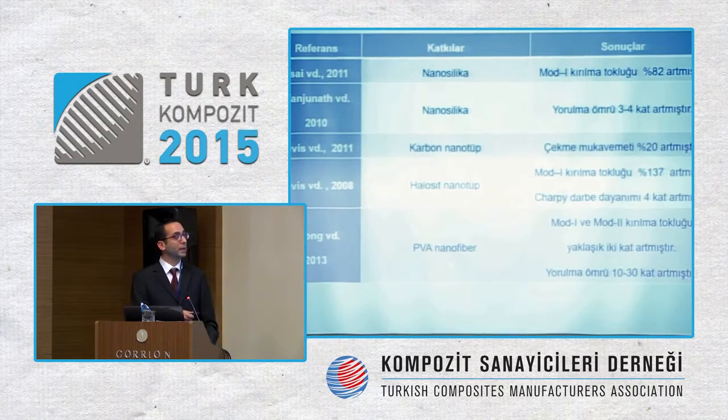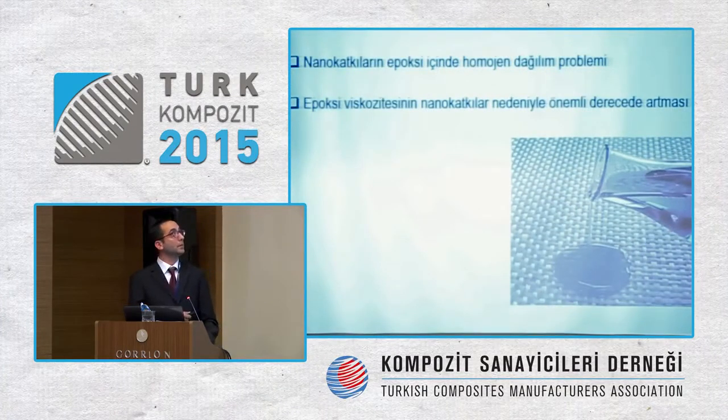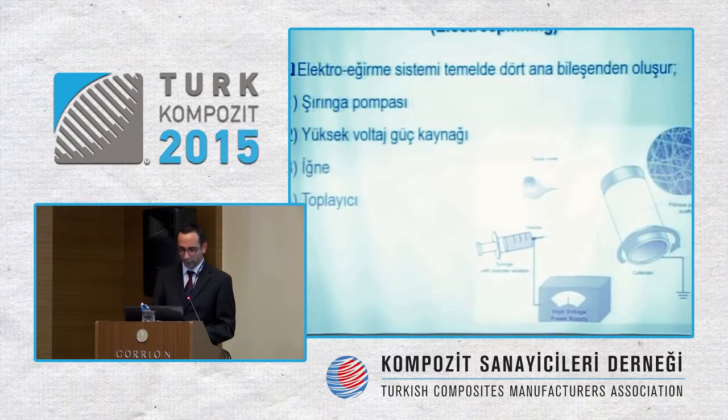And PVA nanofibers, for example, are mixed with epoxy, and mode 1 and mode 2 increase by double, and also the fatigue performance increases. But it's also difficult to homogeneously dilute nanofibers in epoxy, and the viscosity of the epoxy increases dramatically with these additives, and in composite manufacturing during infusion it creates a problem.